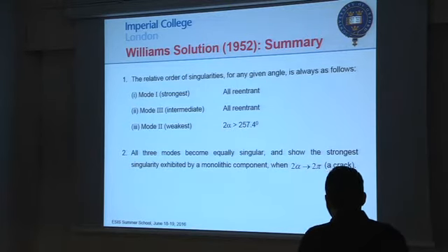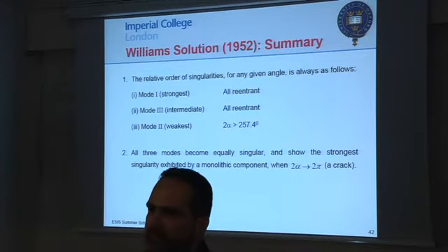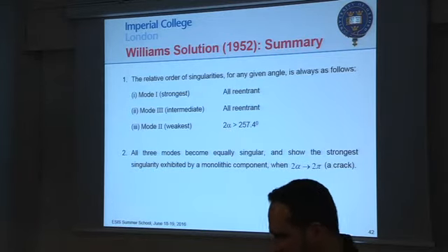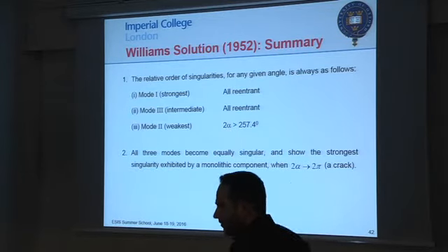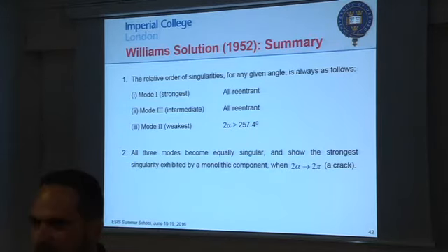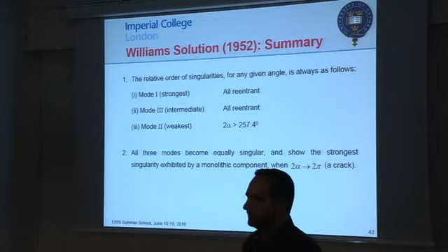And obviously when you go to a crack, all three of them are exactly the same, and they go to 1 over square root of r fields, which are typical of a crack in all three modes. So really the crack is the generic problem of a notch, where all three modes have the same solution in terms of eigenvalues, and they all go to the same stress field.